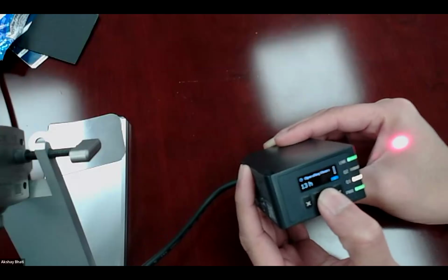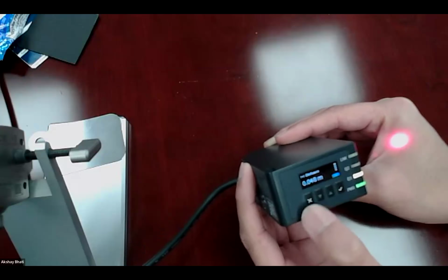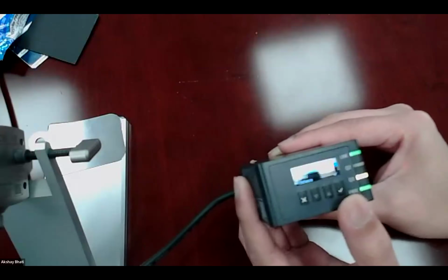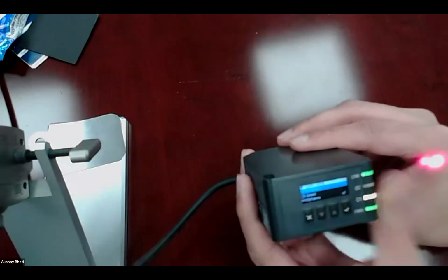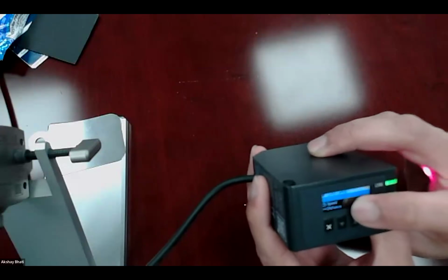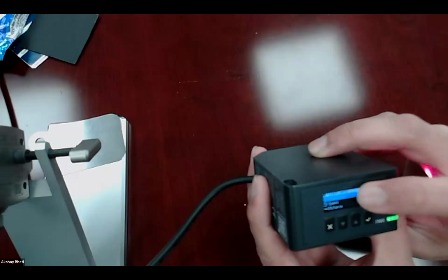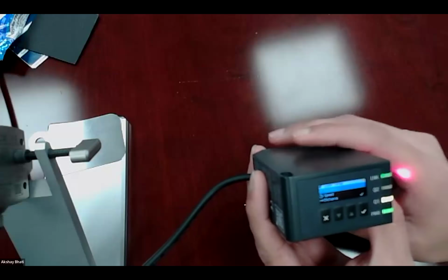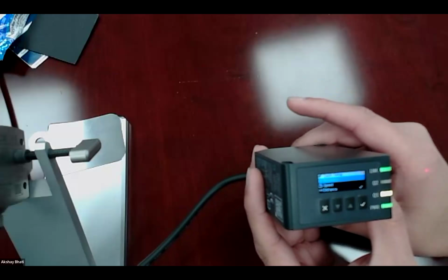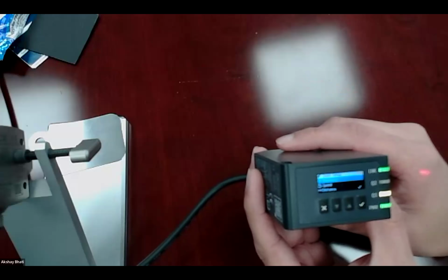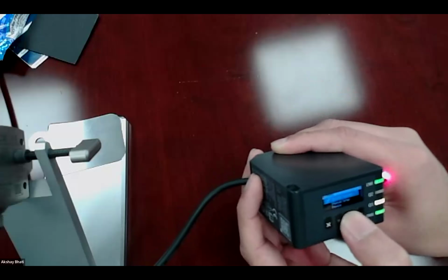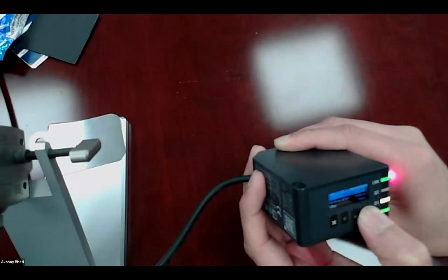Next thing is quick setup. So I'm in a mode which is called quick setup. If it's not clear, then basically the first option is accuracy, speed, and distance. So based on what we need in the application, we can select a mode and then cycle time and response time changes. For example, the response time will be a little bit longer when we are in distance mode because we have to see long distance up to 80 meters.